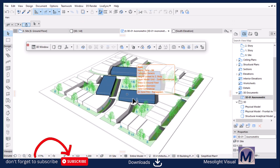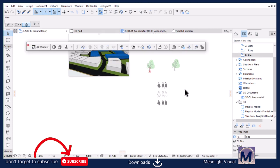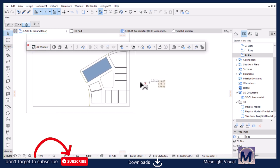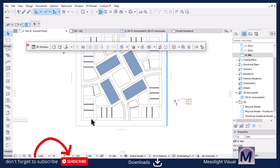Okay, and then the next is to annotate. There are different types of annotation. I can do 3D and 2D annotation. I'll start with 3D because I need to capture the streets for that. So I'll go back to the, let me save this because I'm going to share this file with you. So go down in the link and download the entire file. So I'm going to place the street names just to call out the street names.